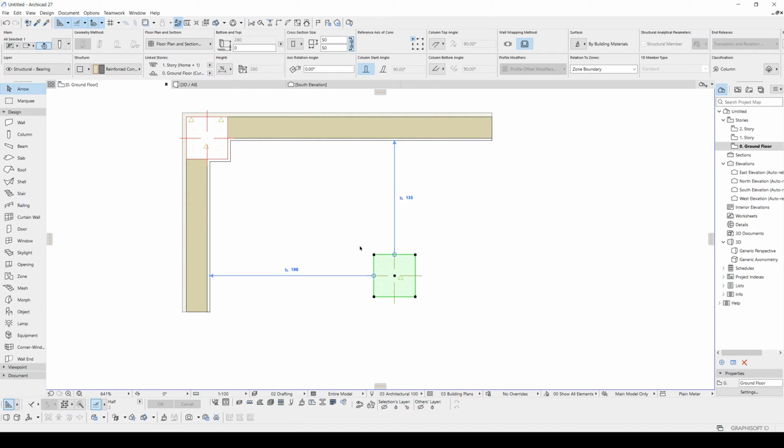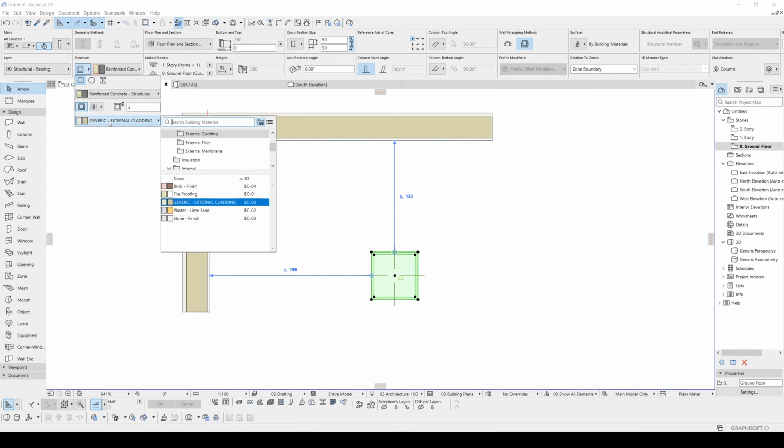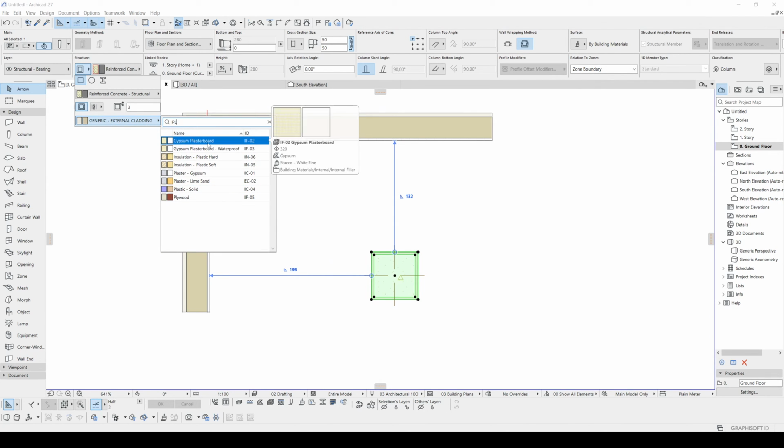That method is changing the structure type of your column. You will go to the structure, click that, and click this veneer, add remove. As you can see, it's been added. Let's change the thickness. Let's make it 3 and make that plaster, this or that.